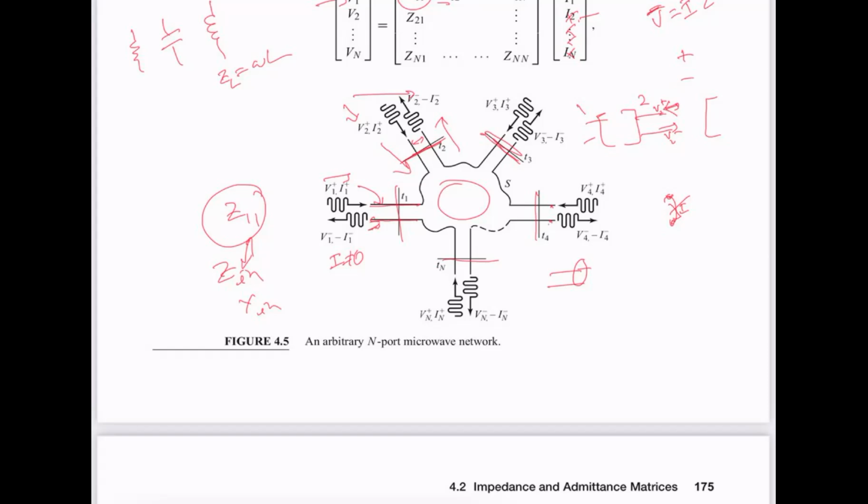We saw the relationship between these two, and then given that you can define the impedance and admittance matrix, which is an extension of Ohm's law, V equals I times Z, to now a matrix form with many ports. We looked at how to compute that for some simple cases, and what the connection is between input impedance and Z11, for example, for a multi-port network.